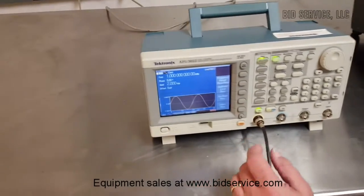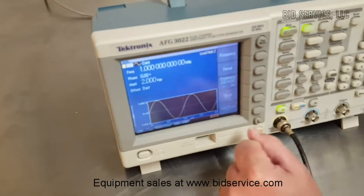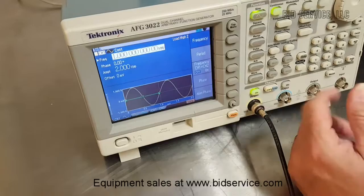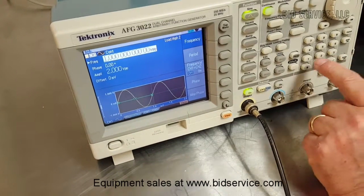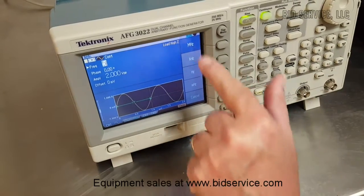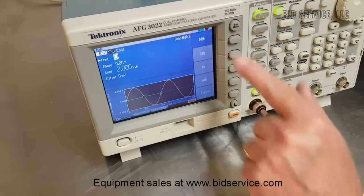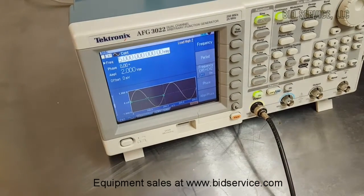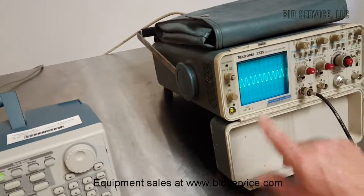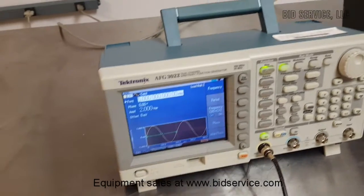So back over to here, I want to show how you can change these things. I want to change the frequency, so I'm going to go into frequency there, and then I can change it to whatever's in range of this particular unit. So I'm going to go to 5 megahertz, and you can see I have my different frequency ranges here. So I'll pick 5 megahertz, and you can see on my oscilloscope here it's changed corresponding to that 5 megahertz.